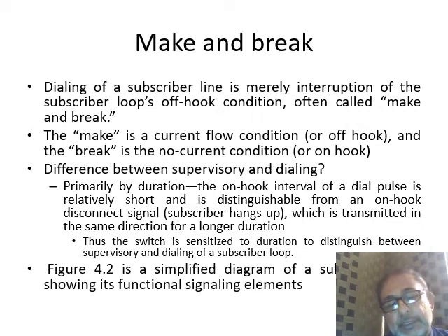This is what a circular dial does, if you have seen one in some older telephone sets. You ring a 0 and you leave it, and it goes back using a spring loading system, and it basically puts on and off the main circuit of the telephone set 10 times. Similarly, if you dial 4, it would make and break 4 times. If you dial 1, it would make and break 1 time.